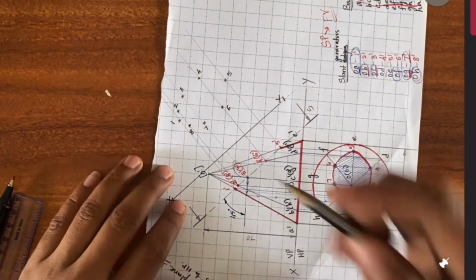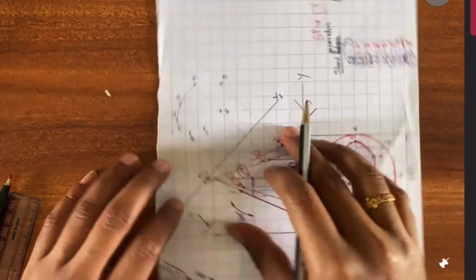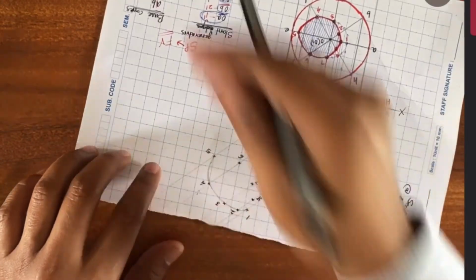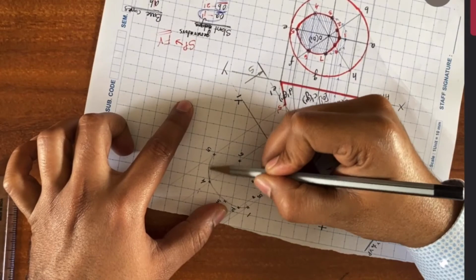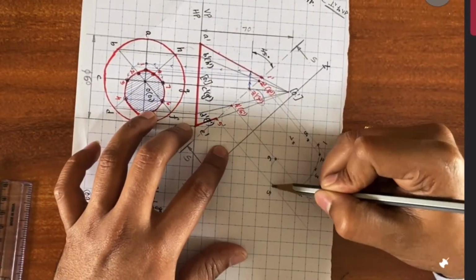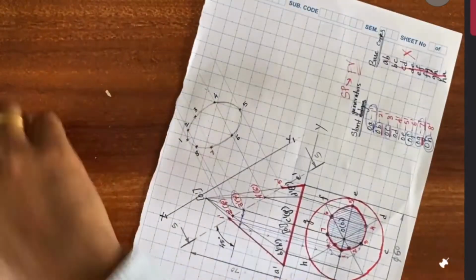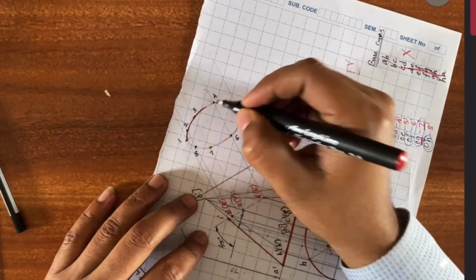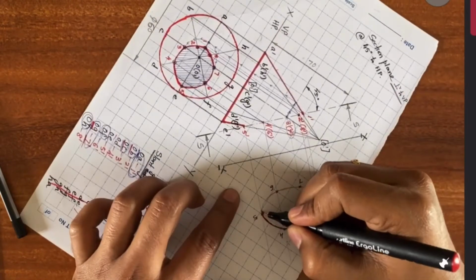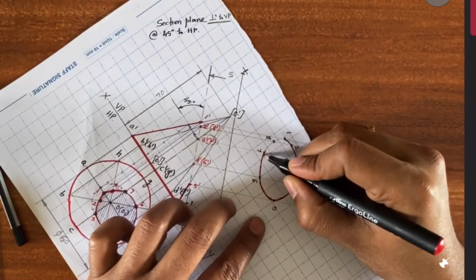And we get all the 8 points from the x1 y1 line. You can join them with a freehand sketch by drawing smooth curve. First you can draw it with thin lines or thin curves, and then you can connect them with darker ones. Make sure that you are drawing smooth curve. It should not be connected with lines since it is a cone.